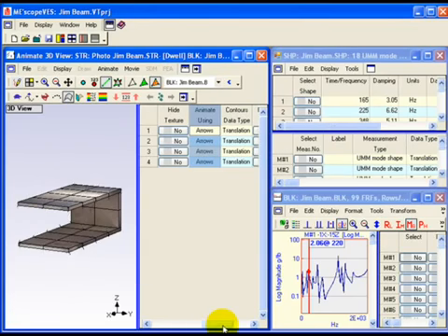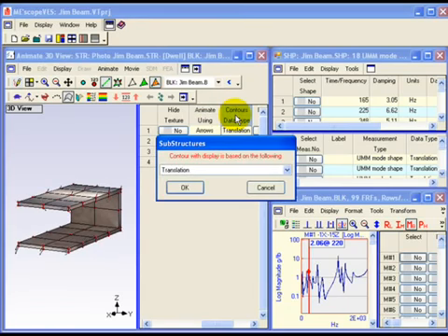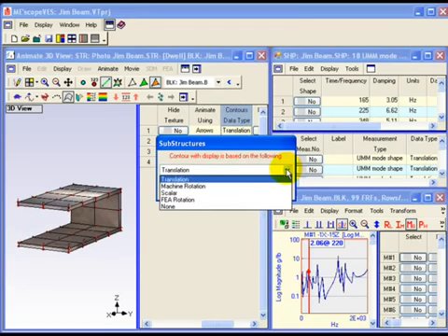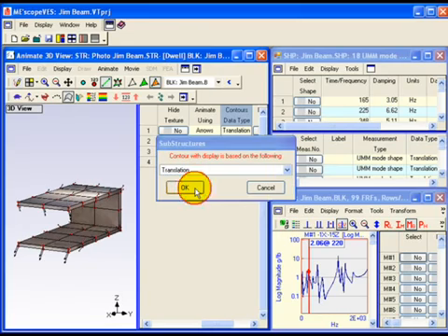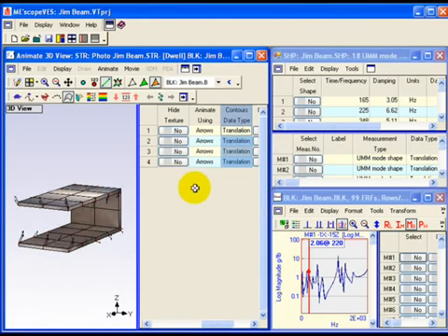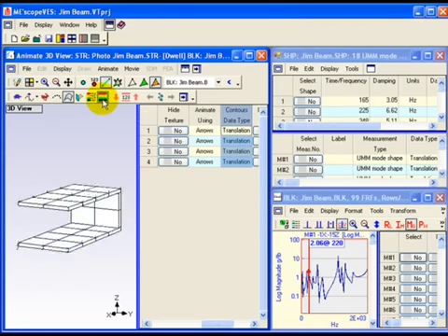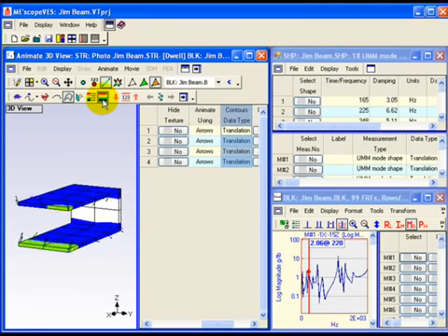Double-click on the Contours Data Type column in the substructure spreadsheet in the Structure window. Select Translation in the dialog box and click on OK. Execute Animate, Contours, Contour Fill to enable or disable the display of shape contour colors on the model surfaces.